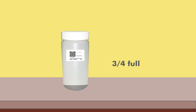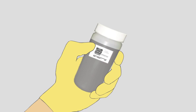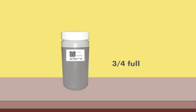You'll also want to make sure the sample bottle is filled about 3/4 of the way, up to but not over the fill line. This allows for any possible expansion and, more importantly, allows the lab to properly agitate the sample prior to testing. This ensures resuspension of any particles or contaminants to achieve accurate and meaningful test results.